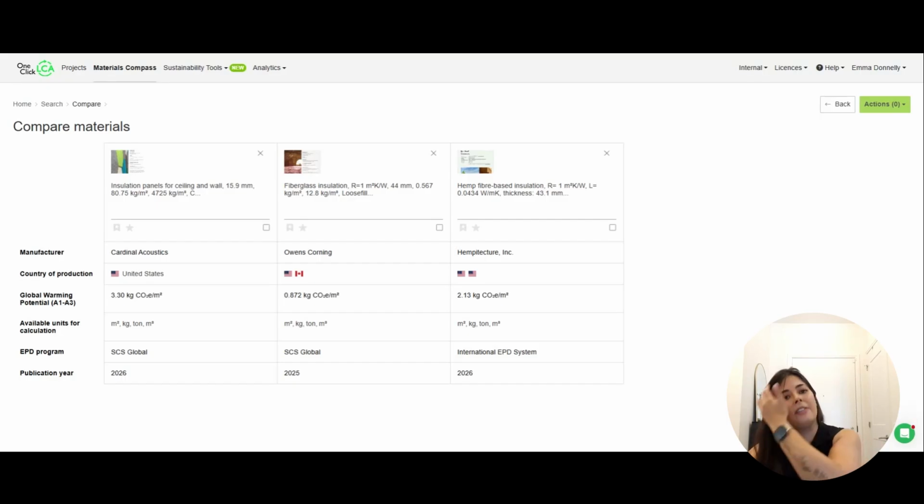And this is where I think LEED v5 becomes really exciting. For the first time, projects are being rewarded for not simply just finding EPDs, but using EPD data to make better material decisions. For a project team pursuing option 2, this can also help identify products that outperform industry averages and support embodied carbon reduction strategies.